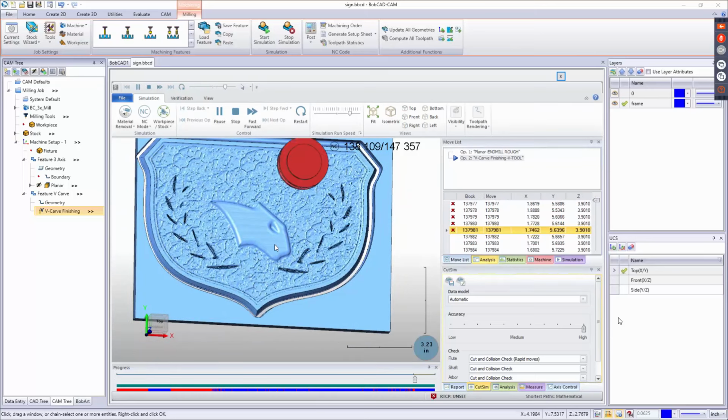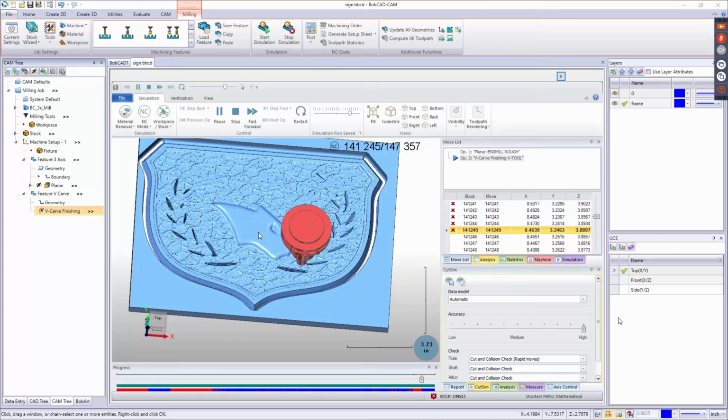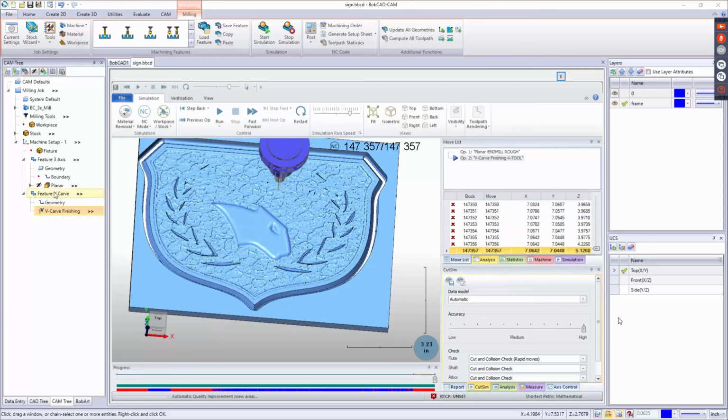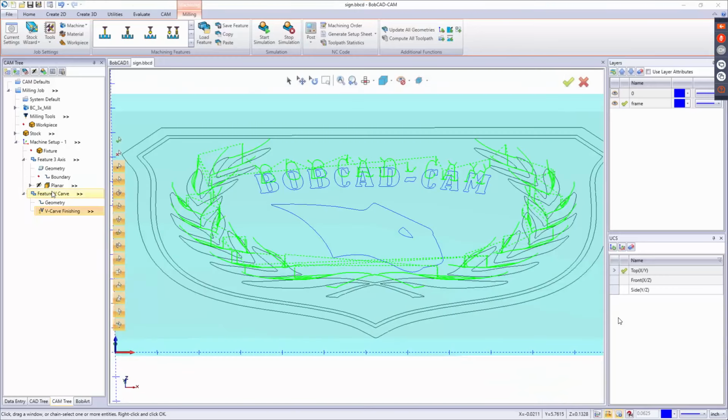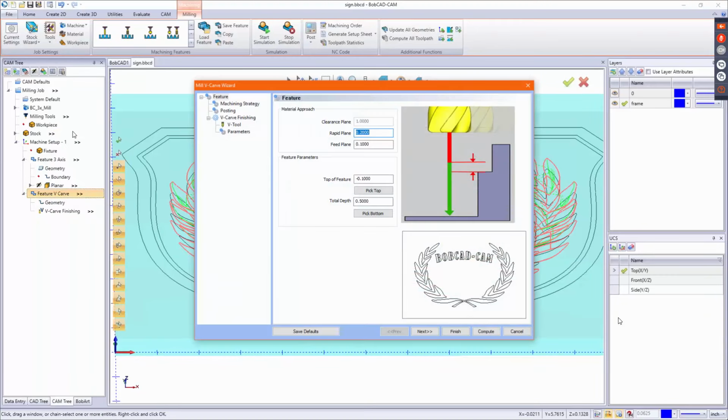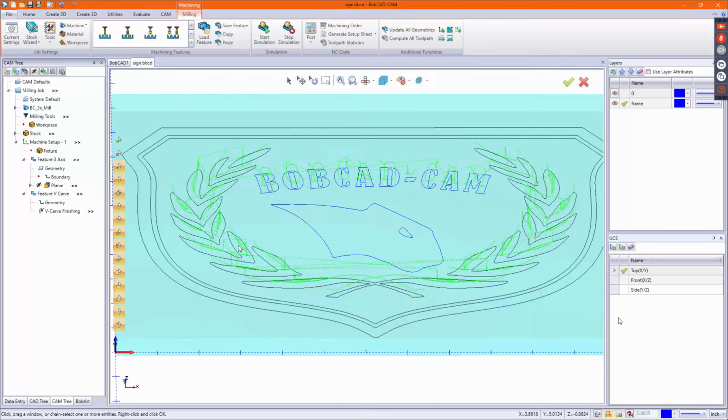I'm curious to see where that V-carve lines up though. So it didn't quite get deep enough on the V-carve. So we have to adjust that depth, that height, where it cuts from. Typically I start at the subtract amount that you give it, and then I modify from there. Let's go another 50 thousandths. Actually, let's say 175. I think it's going to be a little bit more than the 150.